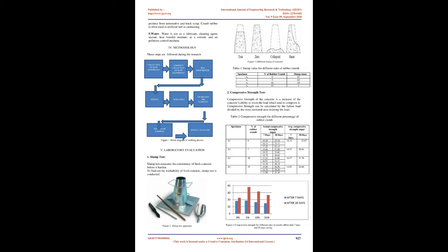Investigation shows that used tires do not decompose under environmental conditions, so burning is the only choice for their decomposition, which causes harmful pollution. On the basis of experiments, we can use these crumb rubber tires in concrete as coarse aggregate. However, this may decrease the compressive strength of concrete, which will be compensated by adding nanosilica to the rubber containing concrete. Objective of the study.